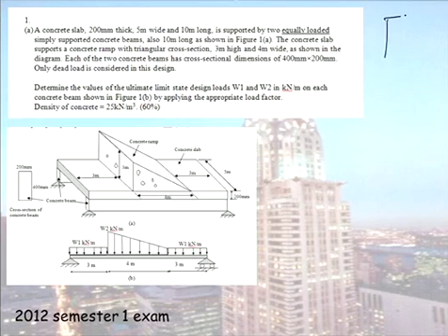Quite often when we give you a beam cross-section, we give it to you as a hollow section. That's because people are not capable under stress conditions of subtracting the inner area from the outer area. So when we ask you a question like this, get that right: it's the outer area take away the inner area. People only take away 1 thickness. When you're given the thickness of the plate, they forget to take away 2 thicknesses. So if you're faced with a question like that, ensure you're working with the right dimensions. This question is solid, so that part of it's easy.